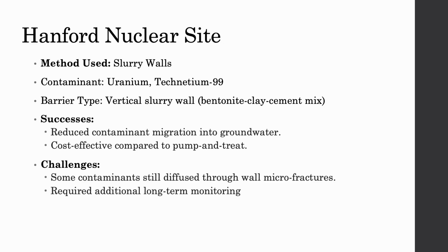In areas with more fractured rock or uneven layering, contaminants had more pathways to escape. So this highlights why detailed site characterization is essential before installing a barrier. It also shows why long-term observation wells are often placed around the perimeters to catch problems early on.